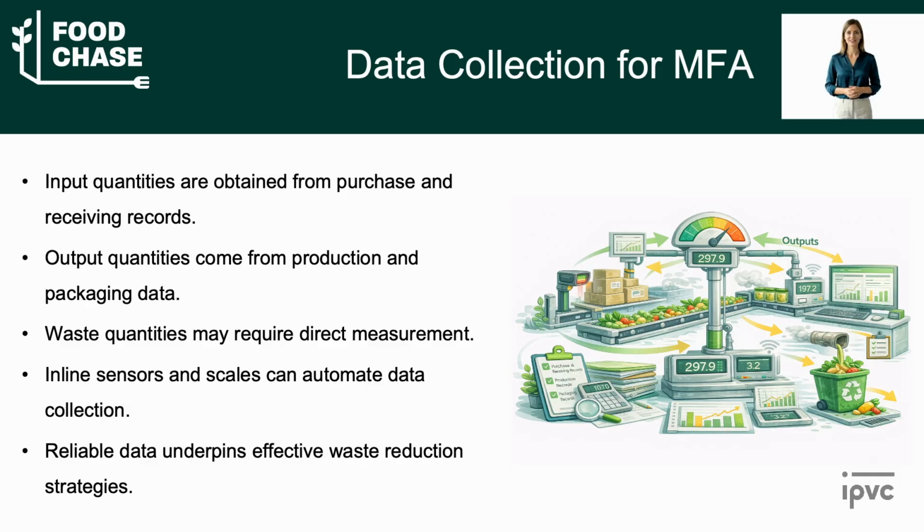Reliable data collection is essential for effective material flow analysis. Input data are typically obtained from purchasing and receiving records, while outputs are measured through production and packaging systems. Waste data may require direct weighing or audits. Increasingly, inline sensors and automated systems support accurate data collection, enabling more precise identification of waste and loss points.